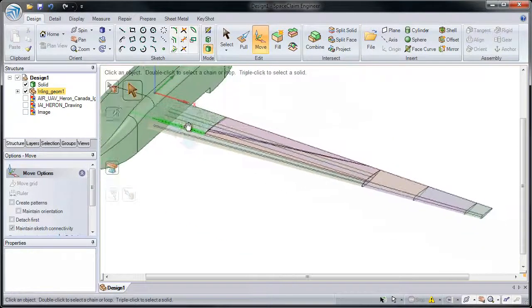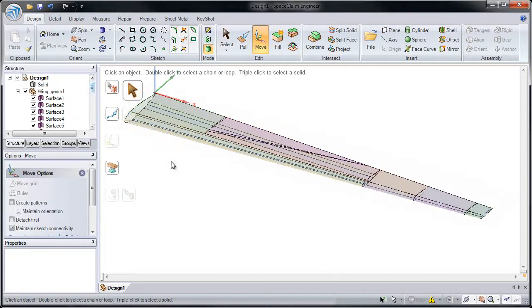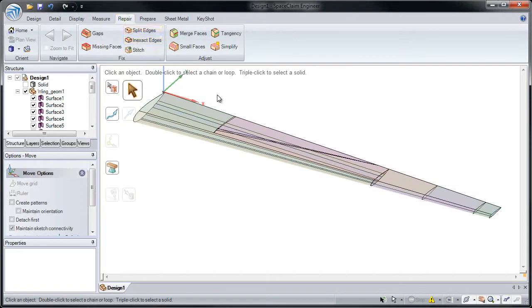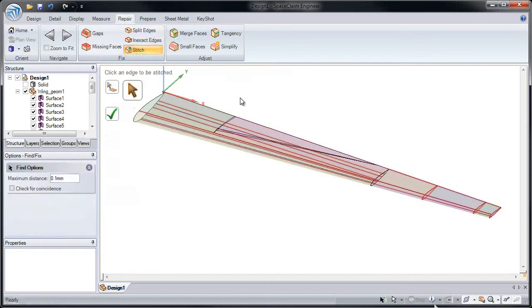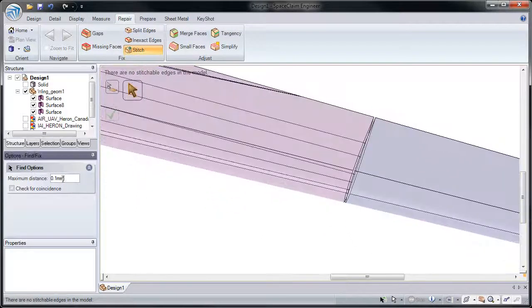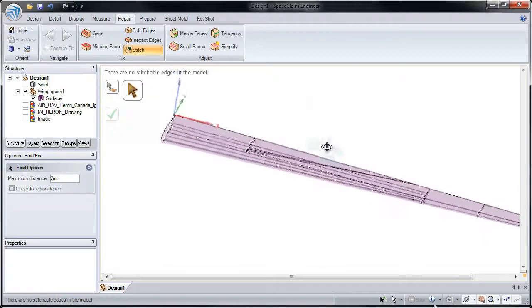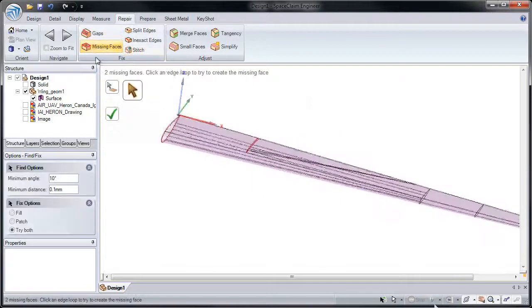And we can import the geometry of a wing. Here we can see that it's come in as several different surfaces from IGES. That can sometimes happen when bringing in geometry from IGES or STEP. And we'll have to use our repair tools to deal with this. We can stitch different areas together, giving us only 3 surfaces, but we may have to adjust the tolerance. Even customizing the tolerance and making these changes are easy because everything you need is displayed for that tool.